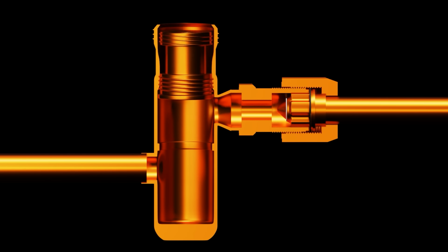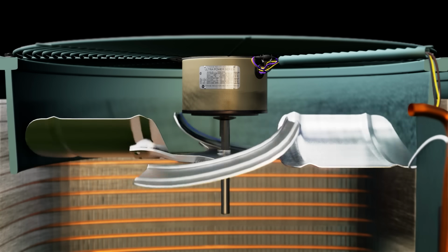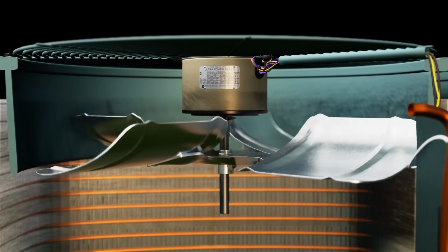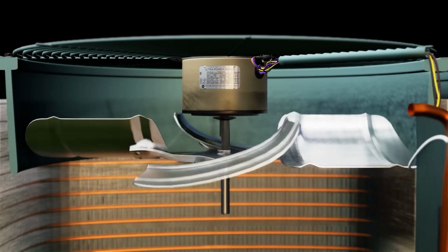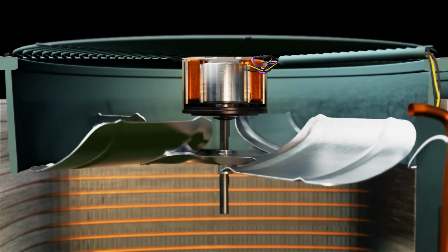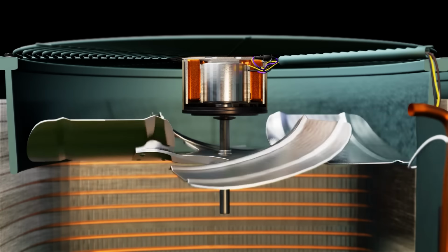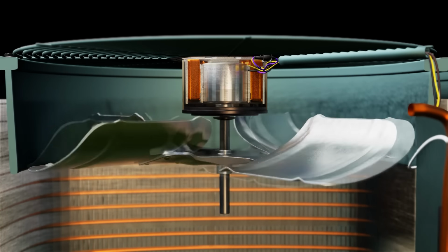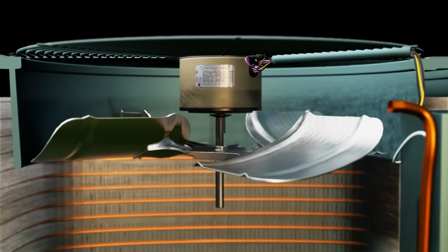Back out at the condensing unit, I also want to show you the condensing fan motor. All fan motors are basically just rotating electromagnets that spin based on the change in frequency of the power coming in from the power company. So in the US, our power shifts 60 times every second, what we call 60 hertz. And so that frequency is utilized in that switching of the electromagnets in order to spin that fan motor. It's important that the blade is positioned properly in the shroud in order to pull air over that condenser coil and blow it out in order to discharge that heat away from the coil.